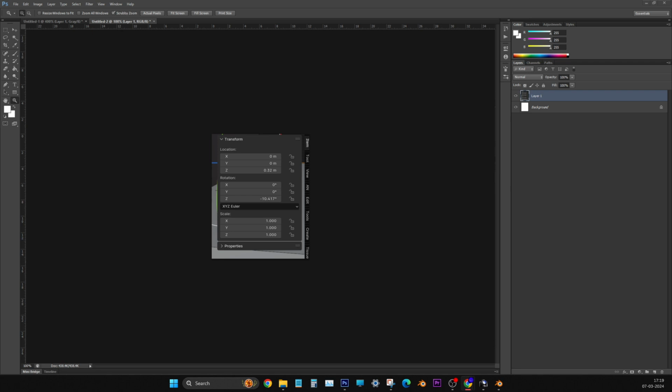Okay, I will tell you. Since you asked me, go to the array modifier settings. There are four icons there, after the array word. Go to the last icon, that next one. Just press there. You will see apply. Just apply it.